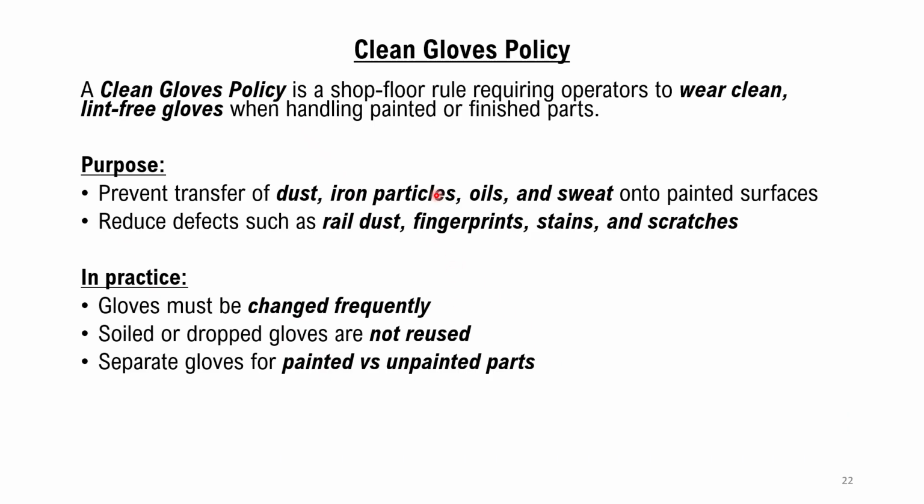The clean glove policy, as mentioned here, is a shop floor rule requiring operators to wear clean, lint-free gloves when handling painted or finished parts. Purpose: prevent transfer of dust, iron particles, oils, and sweat onto the painted surfaces.